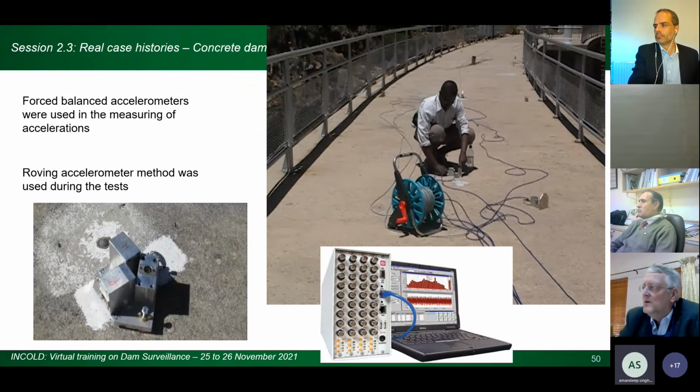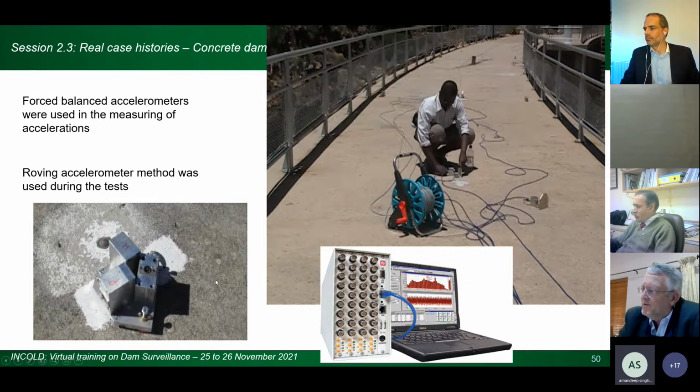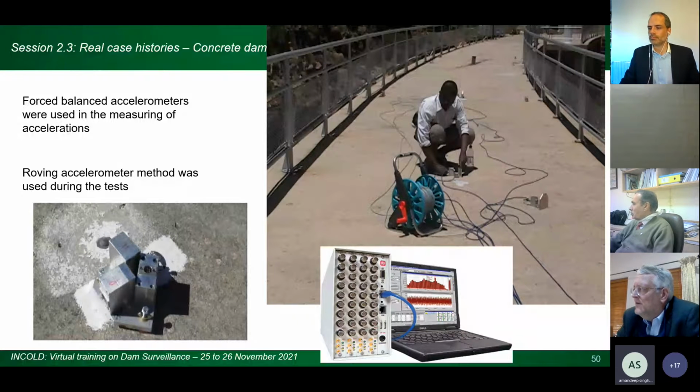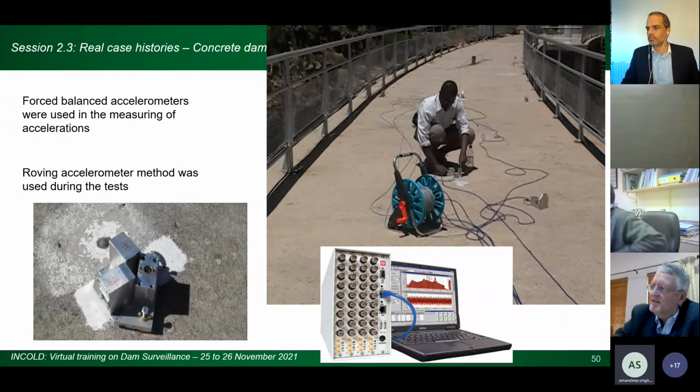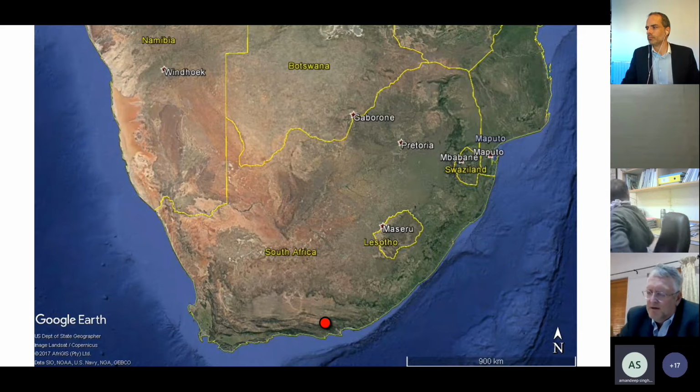of the dam. So there's my friend, Prof. Moyo from Cape Town University. He's really the expert on this here in South Africa. He uses very sensitive accelerometers that were actually developed for space travel. You measure the accelerations on the dam at each block, and as I say, you can convert that to frequencies, natural frequencies and your modal shapes as well.